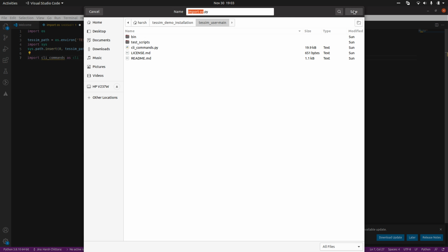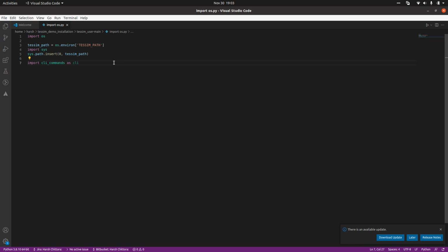You might want these few lines here because it's a local library, so in order to tell Python where to find that library, you'll have to add that path to your Python script, and the first 4 lines are just that. Beyond that, it's normal Python. Now, as I said, for the motor model we will need 2 nodes, and I'll just make nodes equal to CLI.create_nodes(2).